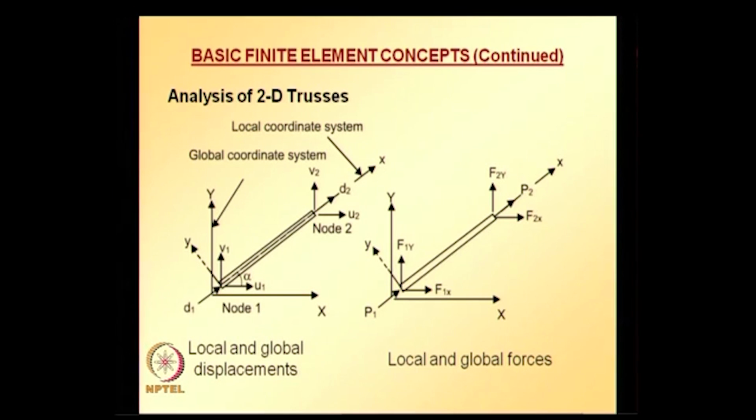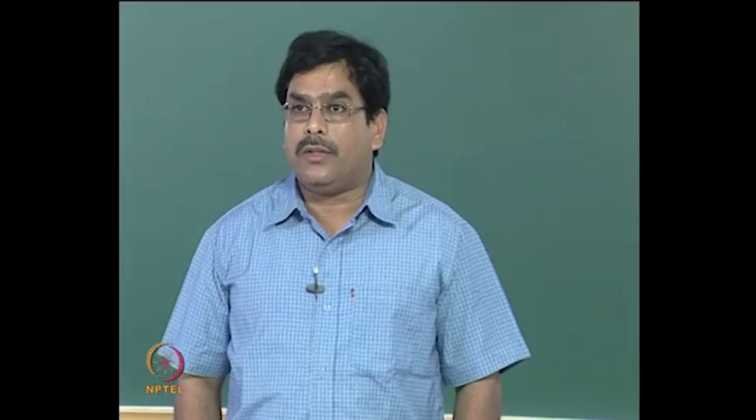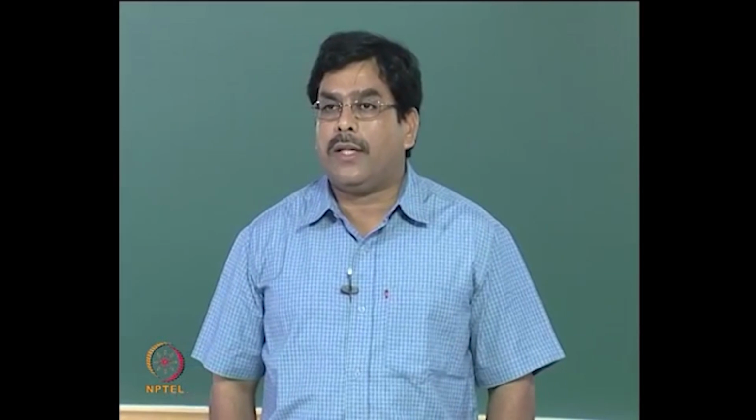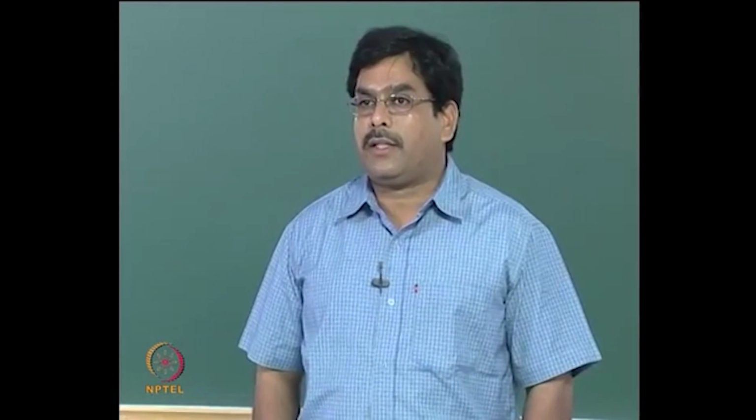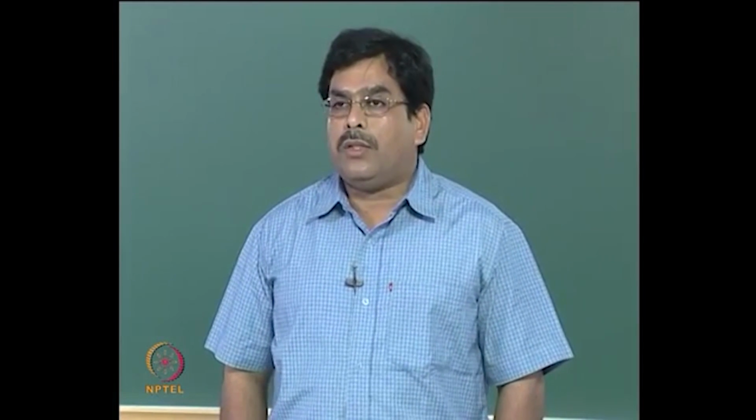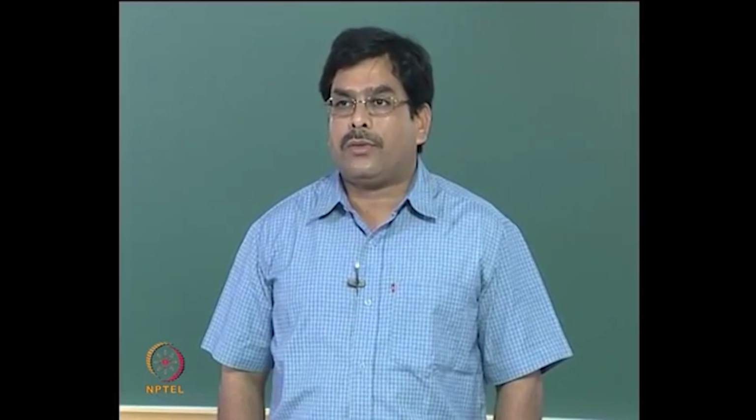These are in the local coordinate system, and these displacements and forces get resolved in the global coordinate system, where the global degrees of freedom are denoted using small u1, small v1 at node 1 and small u2, small v2 at node 2.